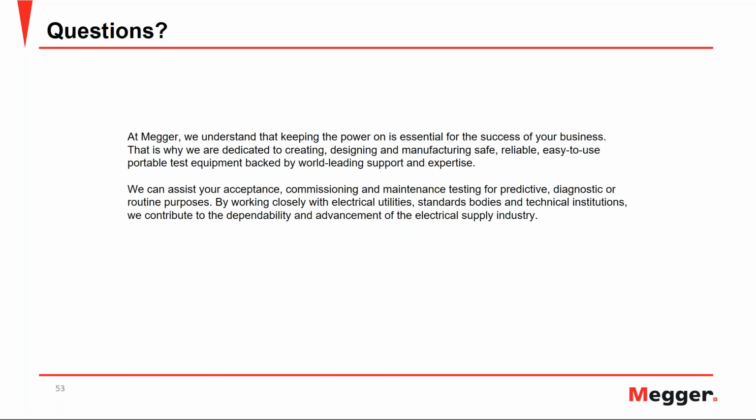One important thing I want to mention here is that it's not just about negative power factor value. Let's say last time when you did the testing, assuming the temperature is the same, your power factor value was 0.5%, and next year you go and the power factor comes out to be 0.35, I wouldn't be happy about that. Insulation cannot improve by itself.